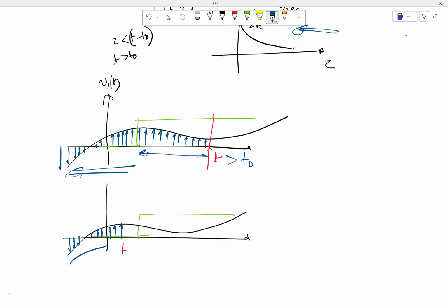For all these cases, it's equivalent to that first impulse response, that is 1 over RC e power minus tau by RC. Once you have that, you do the convolution integral, assuming appropriate limits for each of them, and the final output that you get is your eventual output.